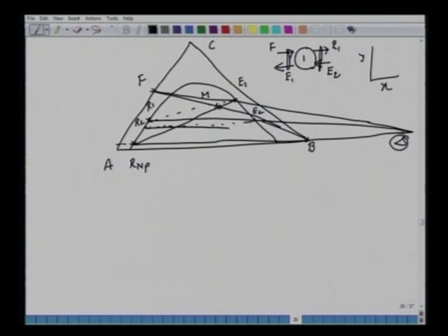Connect this. We have now E3. Take another tie line. We have now R3. Connect this to delta. Mind you, all the equilibrium curve tie lines are dotted and all the operating lines are solid lines. Okay, so we are following the same conventions we had for distillations. So this point here is now E4.